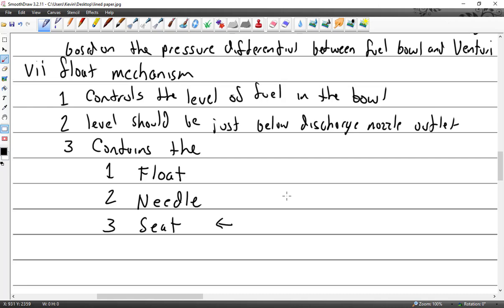Wherever you have blue dye, don't just dismiss it as somebody dropped their Sharpie. You have a leak. There's probably not enough dye in the liquid to stain; it gets concentrated, and then the fuel evaporates and leaves the dye ring there.